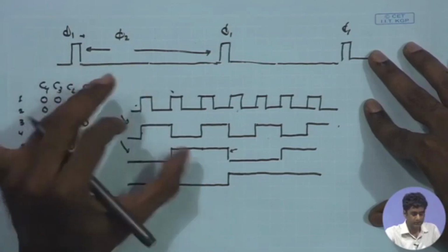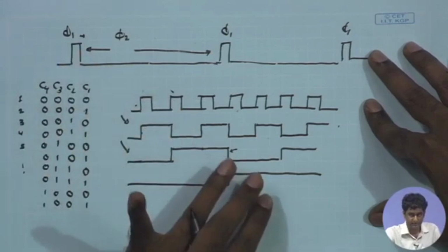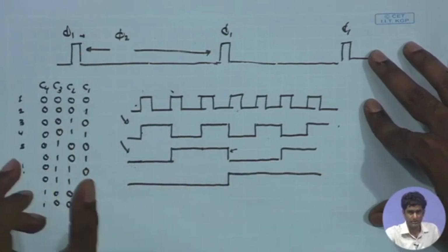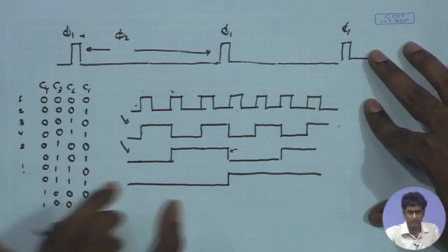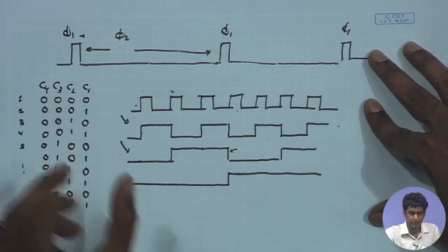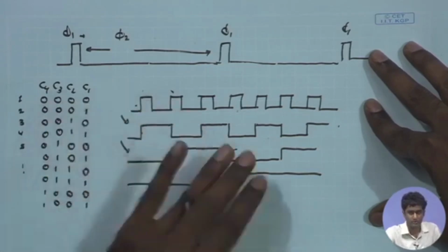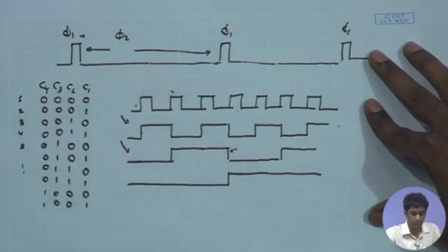So, let us see the definition of level sensitive and edge sensitive blocks, and then look at the definition of flip flop, which is basically a cascade of two opposite phase level sensitive latches, and with the help of that we can see how we are going to construct such a counter which is performing the overall counting operation.